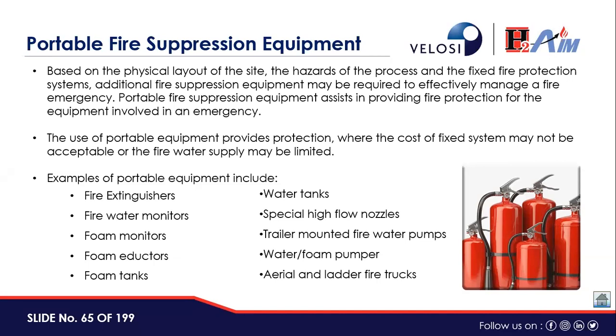Okay. One question from Mr. Nazmi. How do we decide whether we need firewalls or a blast wall for the facilities? How do we calculate the rating of the wall? See, basically QRA studies are run, where the fire zones and contours are determined by the QRA study, and then accordingly the effects are minimized by installing the fire wall.